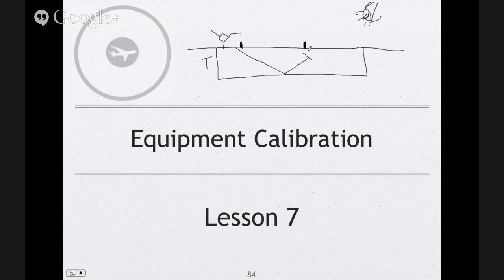And I'm also going to tell you how deep that indication is, from the top surface to the bottom surface, by using some trig functions, sine, cosine, and I think also sine and tangent. We're going to go over how we can use our machines and math, and these angles, to calculate how deep it is here.